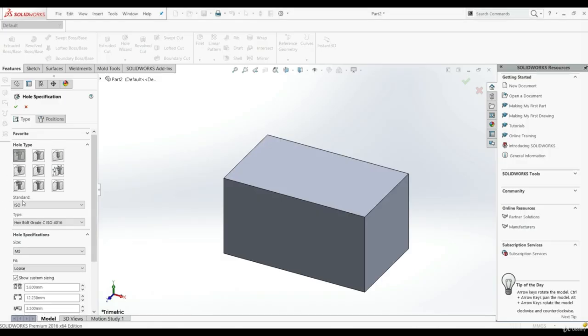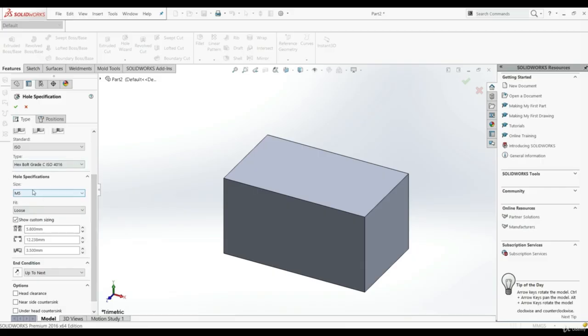The second thing that we can choose is standard. Here we have ISO. We can change this, but let's go with ISO. Here we can choose the type of the hole, and now we have hex bolt. We can go with hex screw, hex socket, pan head, slotted cheese, and so on. Let's go with hex bolt, like this. Then we have hole specifications, M5, M6, M8, M10, and so on. Let's go with M8.